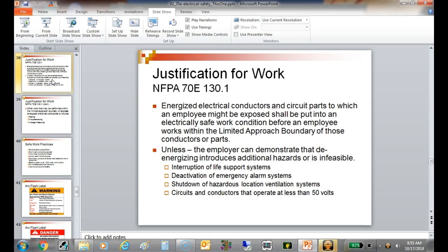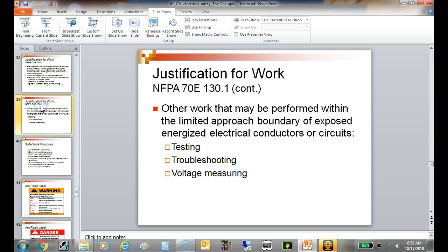What we do now is we rate meters in categories. I'll show y'all later on, but down at the bottom of this meter, in fact, I'll just pass it around and I'll put it up on the video later on. This is a category 2 meter, and a category 3 meter right here. Now what the category displays, it tells us how much surge. Later on, I'll show y'all a chart that shows you that.